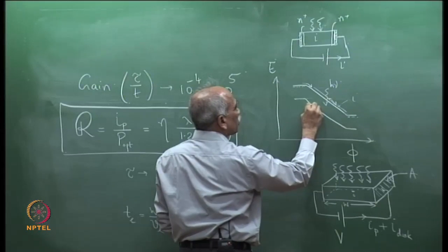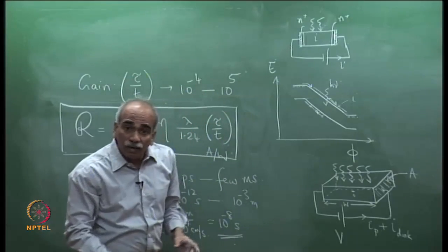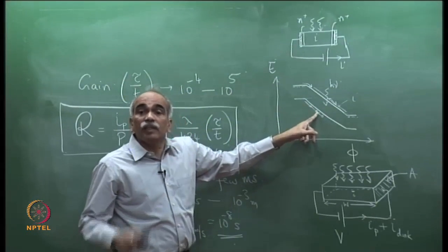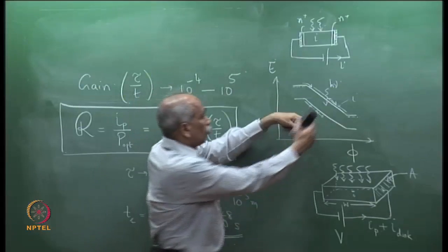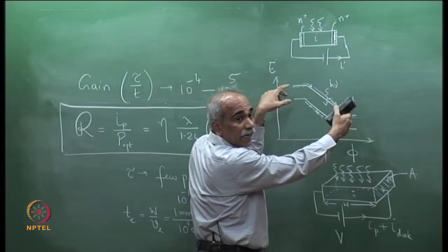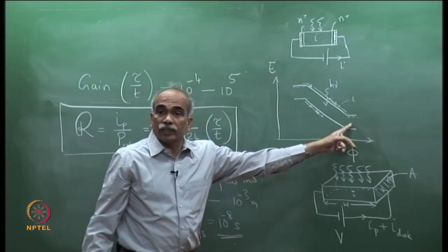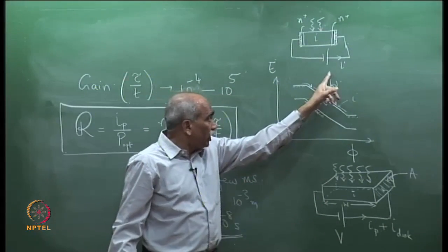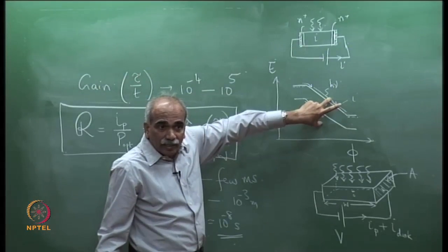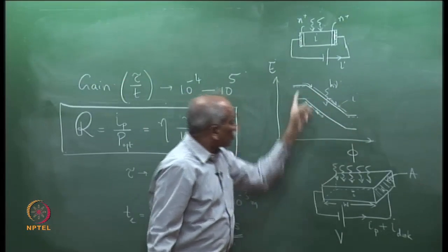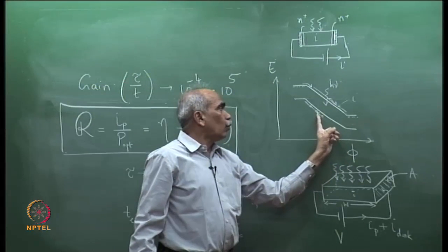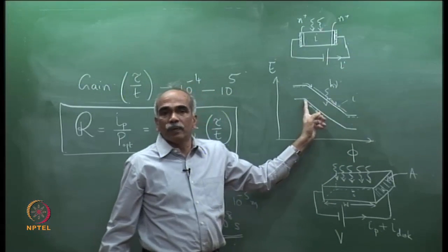This proceeds until either the electron and hole recombine in the medium or both are collected by the contact electrodes at the ends. Please see, there was only one photon incident, and one carrier pair generated, but so many electrons were transiting through by the time one hole was travelling up.